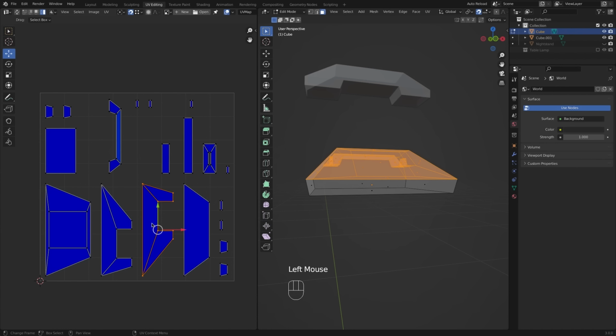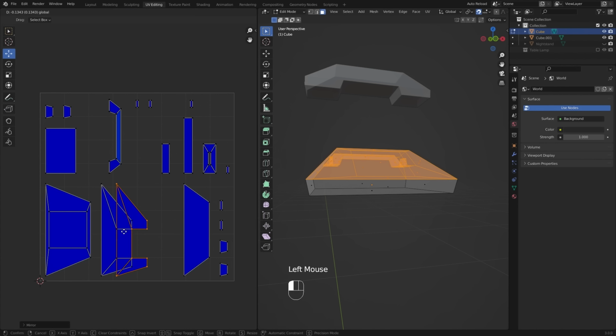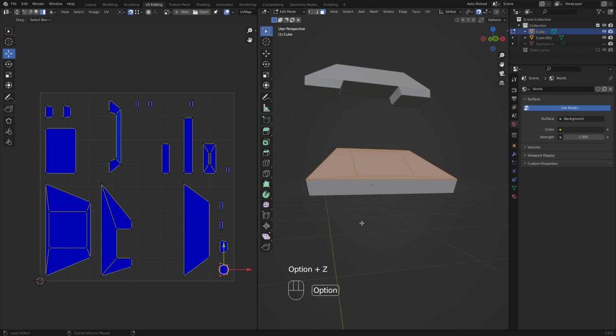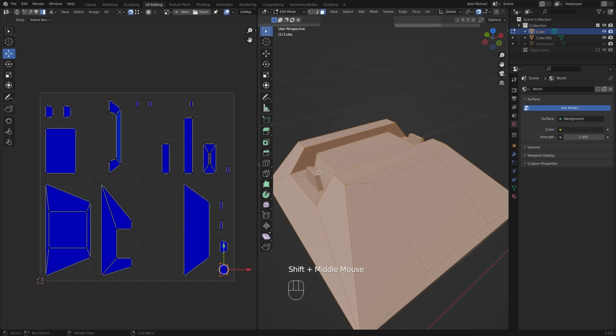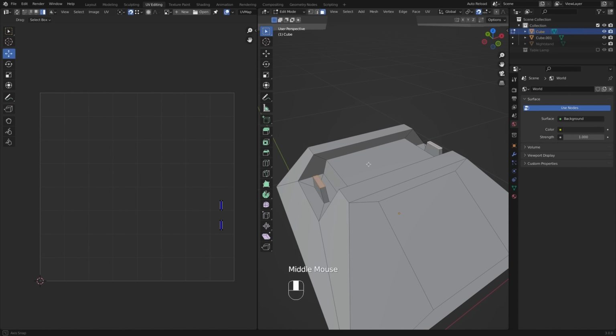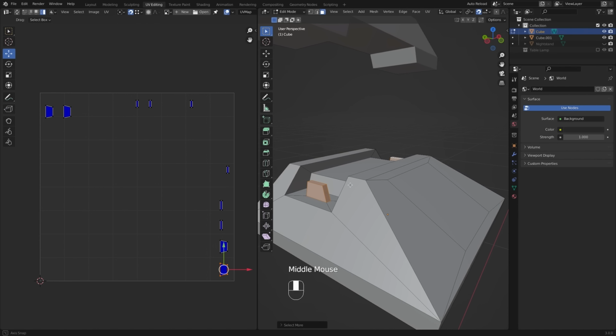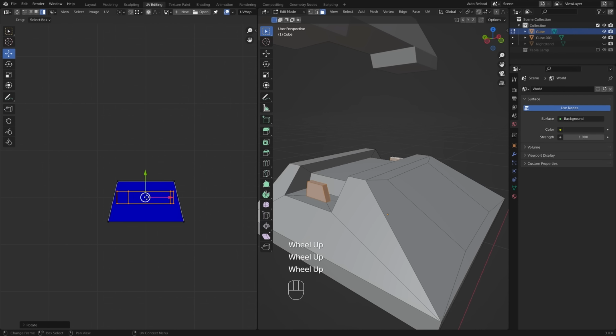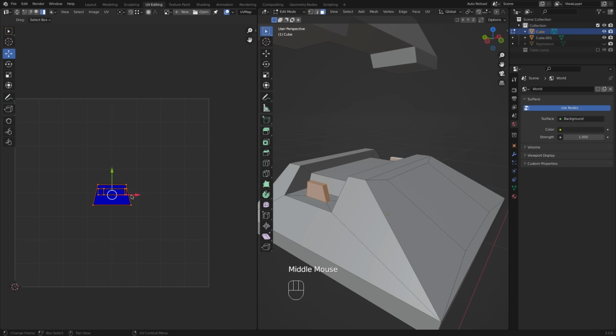To properly rotate this part, just right click and select Mirror Y. Now to avoid joining the small elements, press Alt Z to disable X-ray and select these two faces. Then press Ctrl and plus. This command adds the following faces to the selection. Then go to UV and Q projection. Join these two parts, then disable snap and place them like this. Move it to the side for now.